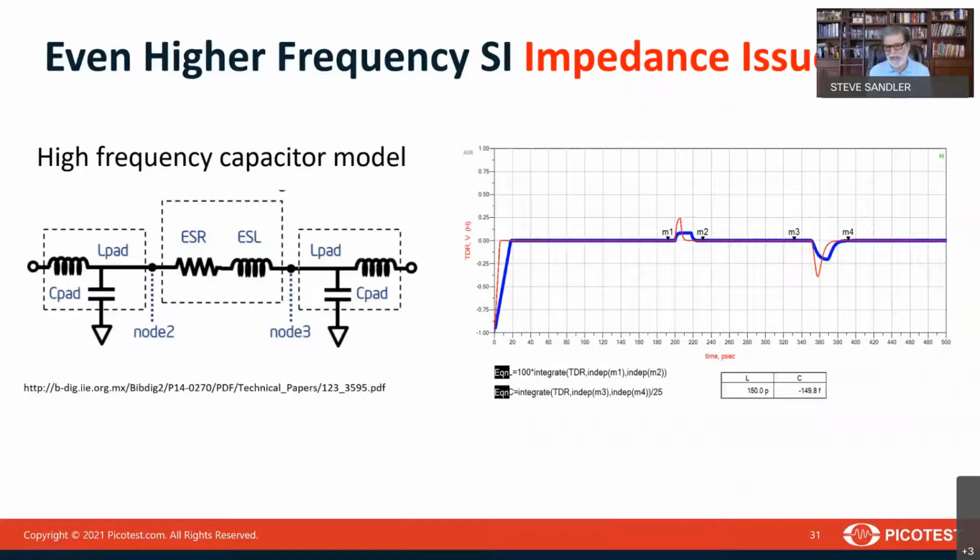Some of these parasitics get really small, and how can we measure them? Well, one easy way when they get really small is to measure them using time domain reflectometry. Time domain reflectometers get to relatively high frequencies at relatively low cost. At about 10 gigahertz, it's pretty easy for us to measure femtofarads and picohenries. One way that we can measure those parasitics is just to put a TDR response where the switches are and measure that response.